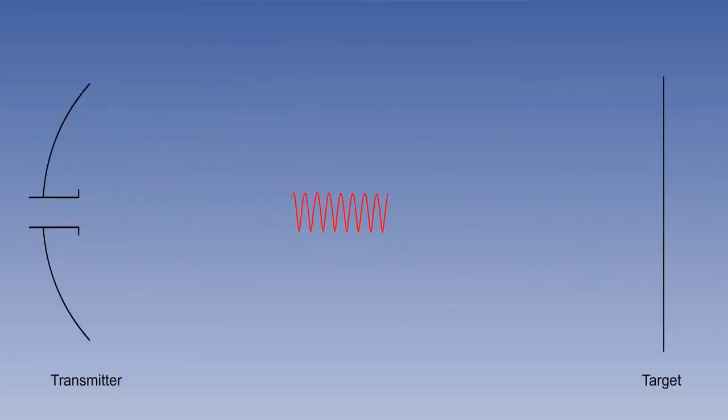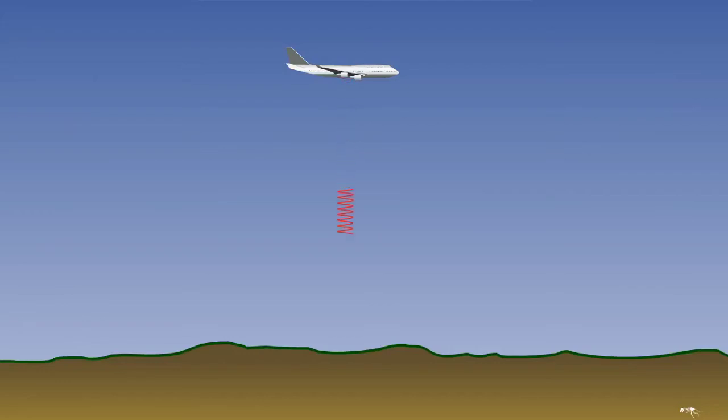Traditional radar uses pulse modulation, that is, a short pulse of energy is sent out. The returned echo is received before sending out the next one. The time interval between transmission and reception is measured, then divided by 2 to give the time for a one-way path. Radio waves travel at 300 million meters per second, so the radar can display this time as a distance. This sort of technique has been used for high-level radio altimeters in the past, but is not suitable for the low-level situation, especially where great accuracy is needed.